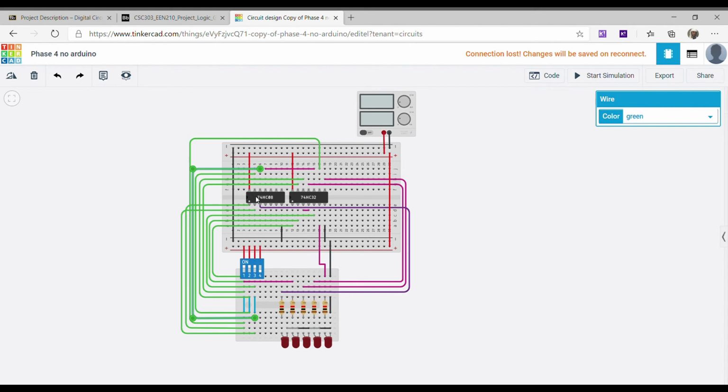This is the IC of the AND gate. So here the inputs are B and C. This one B and this one C. The output will be connected with the OR gate. The second input will be connected with A, and that will make A plus B times C. Then the output will be connected with L3, here with a resistor and simply with the LED.